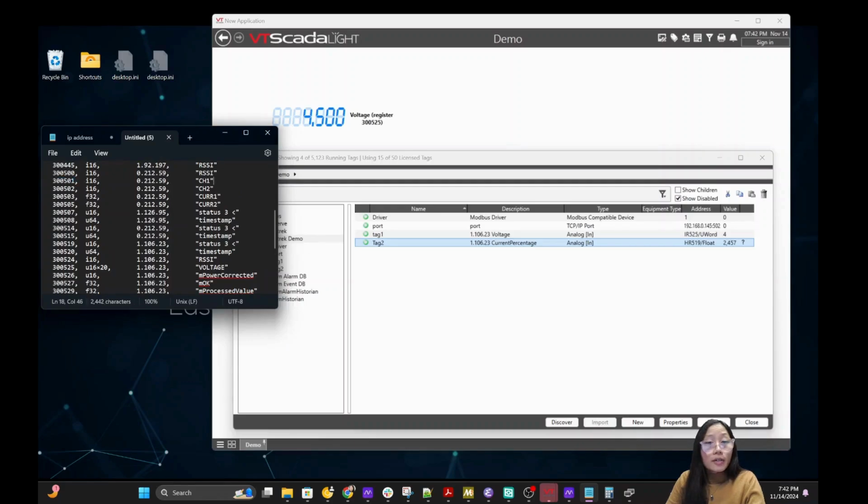501. So it's a 16-bit integer, but I know that normally this is a Boolean. How would I know that? Well, normally I would go into the data sheet of that sensor. It doesn't say which type it is, but I guess you can infer that with the MAC address. The MAC address is on the barcode of the sensor. So I know that this sensor is a relay.